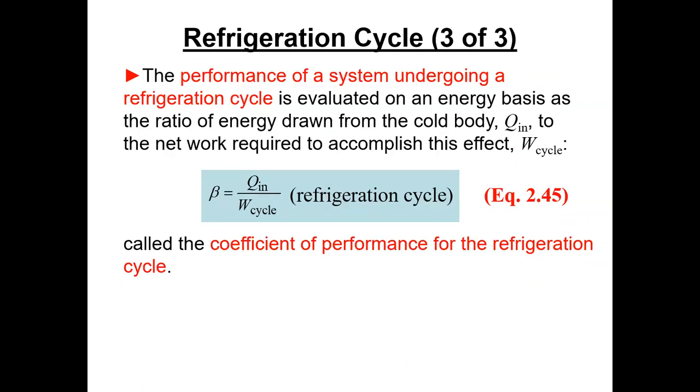Okay, and so now this is our efficiency. But we don't call it an efficiency, because I think I mentioned the other day, we call this a coefficient of performance. But if you look at it, it's the desired effect divided by the costly input. Well, I got news, that's an efficiency. But because it's a number greater than 1, we don't call it that. We change the number. So this is the old COP. And you need to know, that's one of those things you ought to memorize.